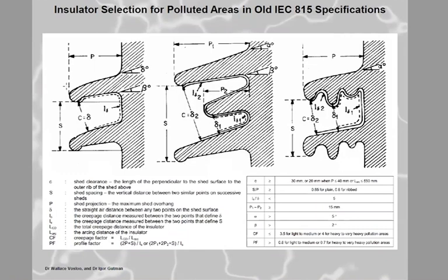And then you would also say, I don't want a drip lip, because that was an idea for porcelain at its time. Here you can see the alternating shed profiles, and here you can see the underribs. I don't want any underribs because they're going to be collecting pollution. So that's how you can spec. It was nice and simple, and everybody was hunky-dory.